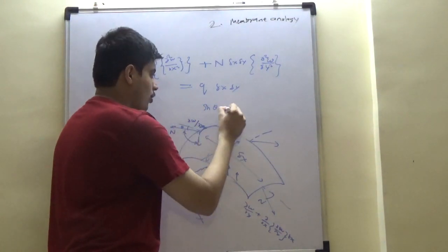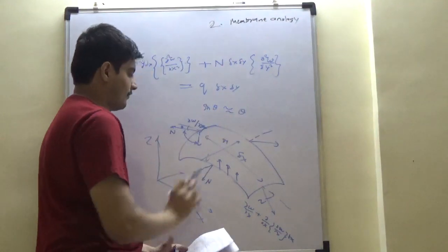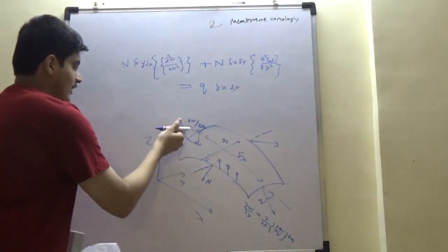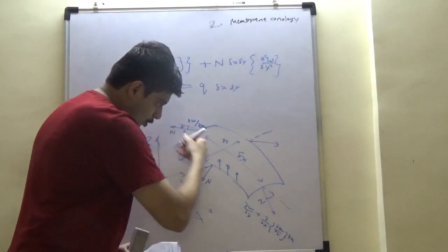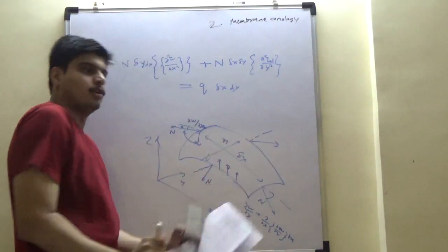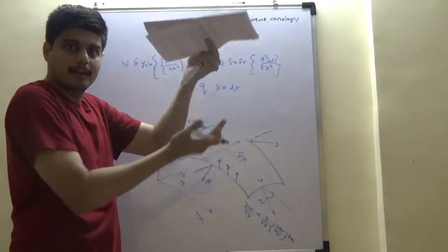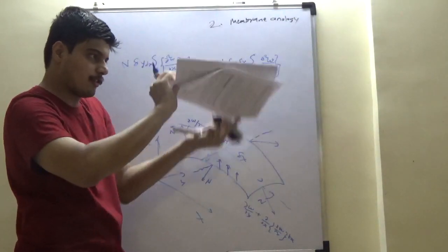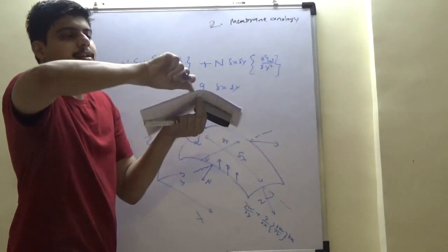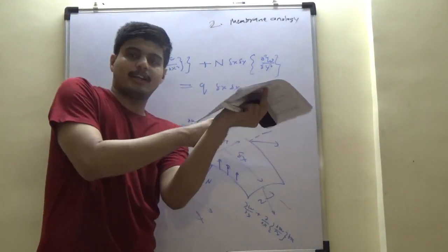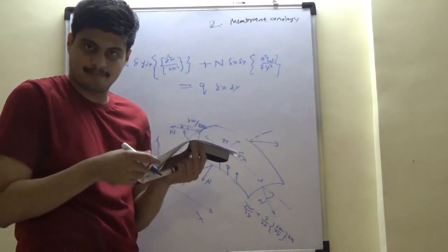But when theta is small, sine theta is approximately theta, correct? So what we have done is we have taken the vertical projections of loads from here which oppose this load which is trying to bulge this membrane from the bottom, the components of the force which are projecting in this direction, similarly the component of force projecting from this direction, all the four sides.